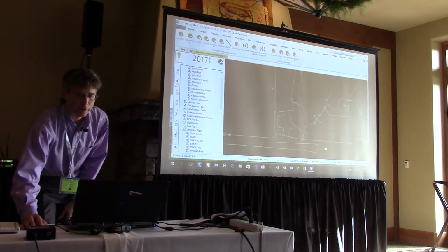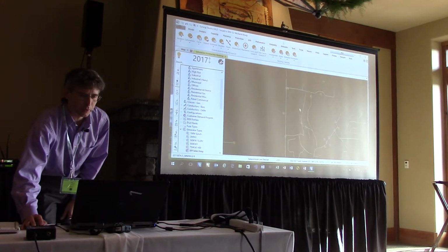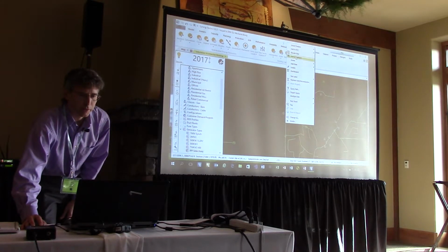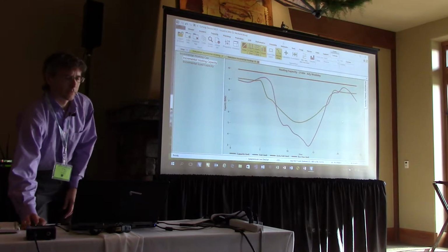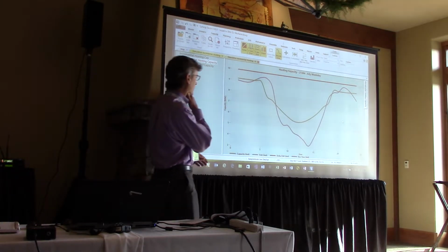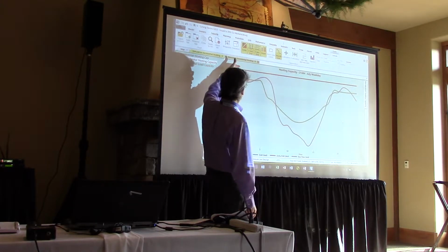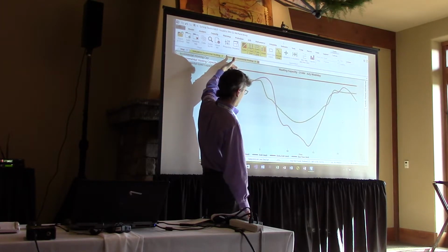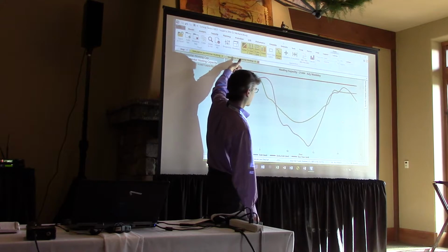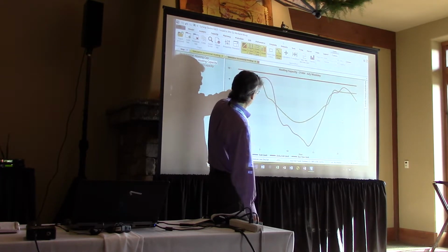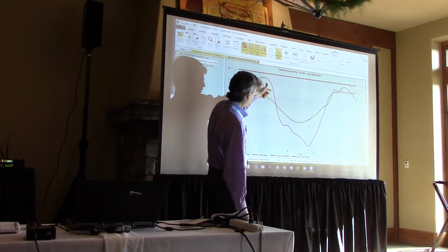So let's try some different locations there. This one was out further. I'm just picking one feeder so it runs quick. Come in here and set this section for analysis, and let's run it here and see what happens. So now here we see the reverse flow limit is the dominant curve. The other two aren't even, I could put 10 megawatts here and not have a problem with, I can't even tell the colors, it's so bright here. But so this is thermal limit, this is reverse flow.